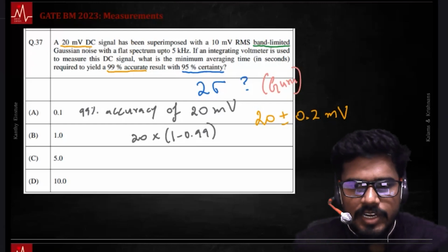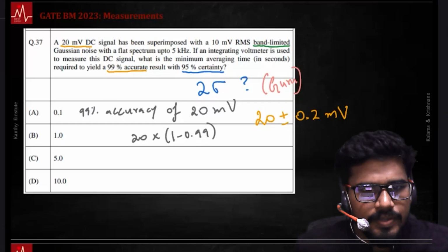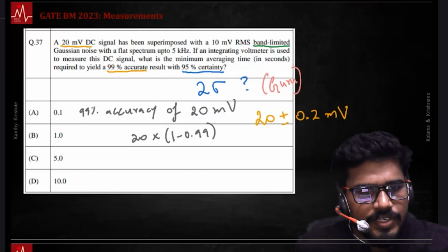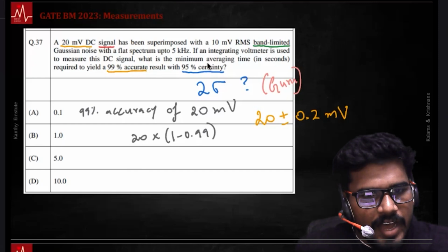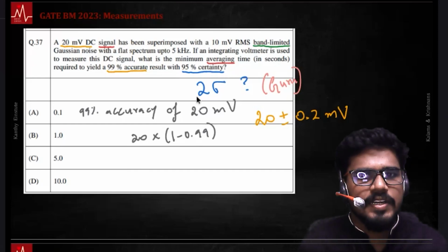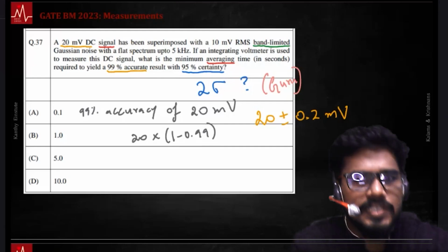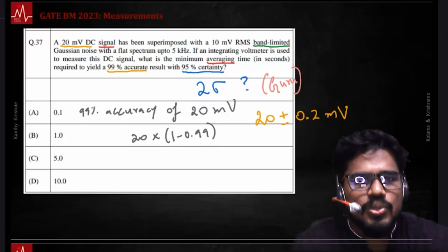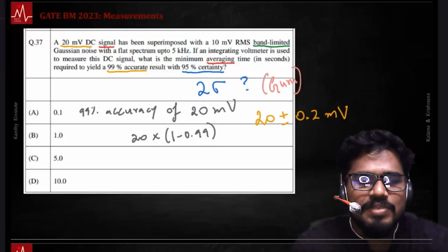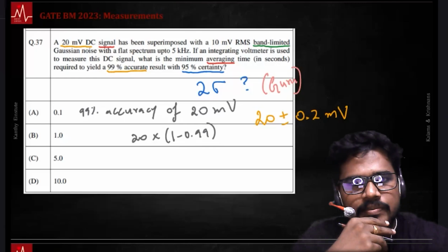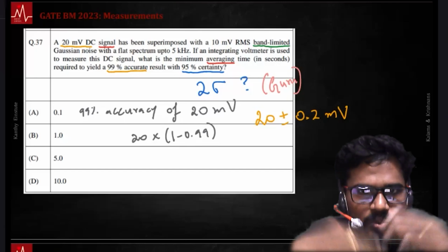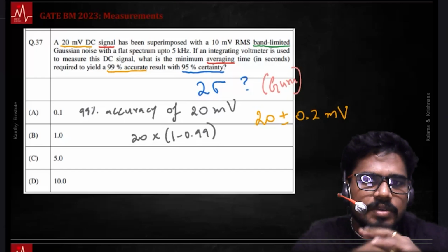One more concept, actually, let me underline the concept. You're dealing with a signal and you're averaging it. There is something called signal averaging. There is noise in the signal, there is noise in the ECG, standard deviation in the noises. You take n ECG samples, take the average of n samples, the noise decreases because the random things get cancelled on an average. So the standard deviation of noise brings down.